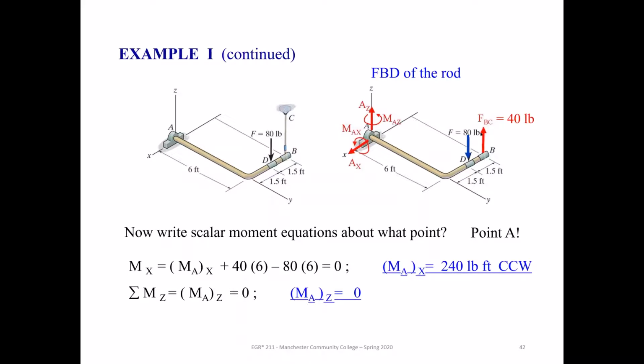These two are parallel with Z, so they have no impact on that rotation about the Z axis, okay? So with that in mind, these are the only two forces involved. The reaction is on a totally different axis, so it actually goes right through this. It's 90 degrees off from this, so it has no impact on it.